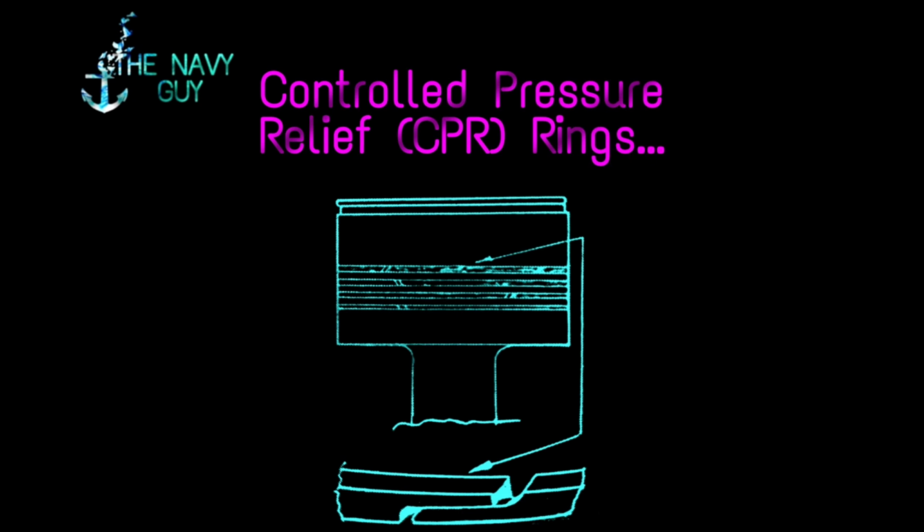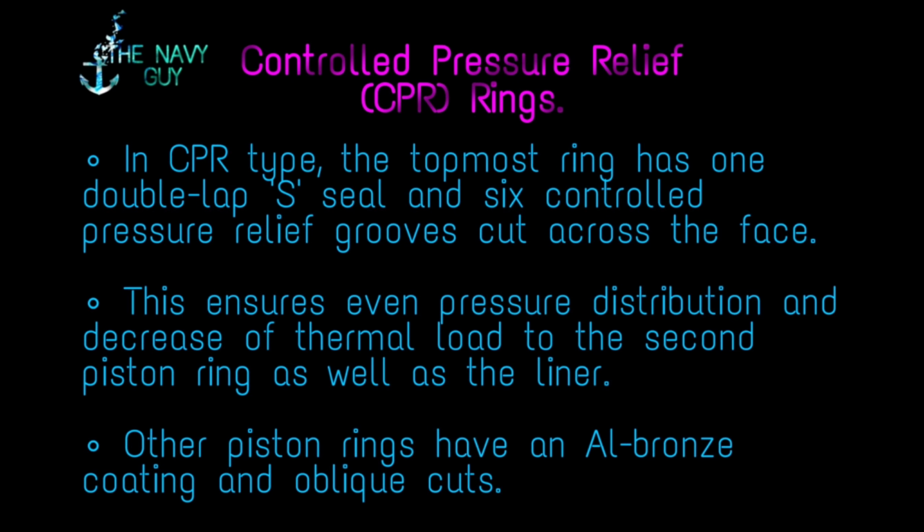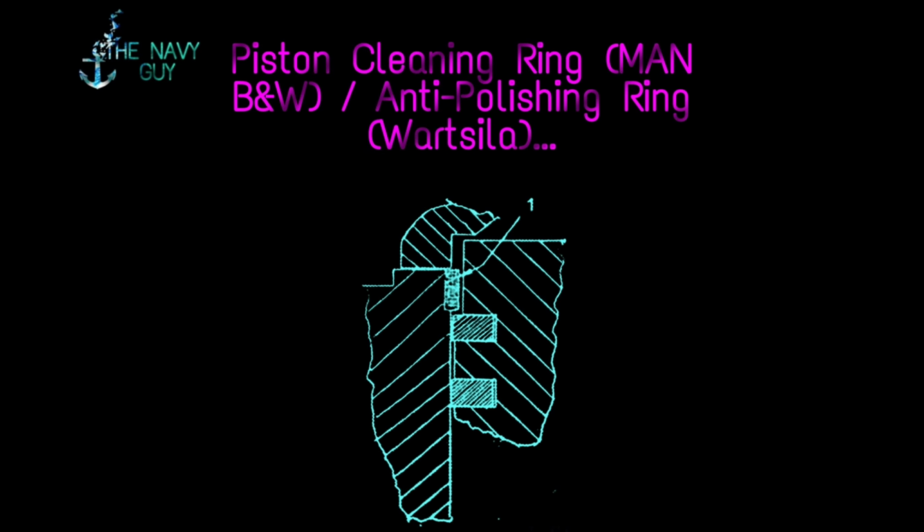Controlled pressure relief, CPR, rings. In CPR type, the topmost ring has 1 double lap seal and 6 controlled pressure relief grooves cut across the face. This ensures even pressure distribution and decrease of thermal load to the second piston ring as well as the liner. Other piston rings have an Al bronze coating and oblique cuts. Piston cleaning ring, MAN B&W.